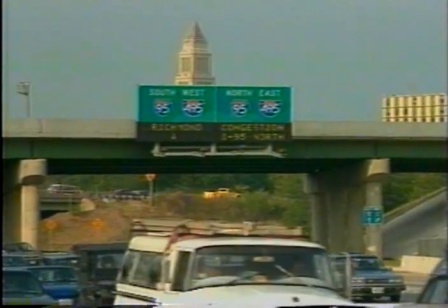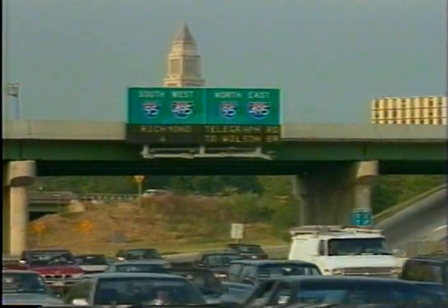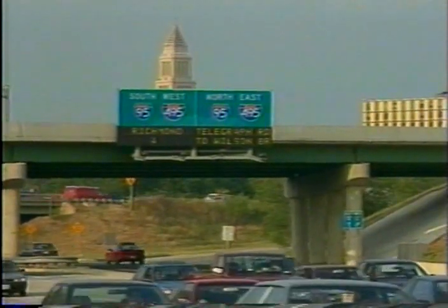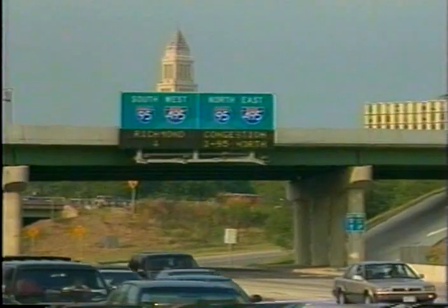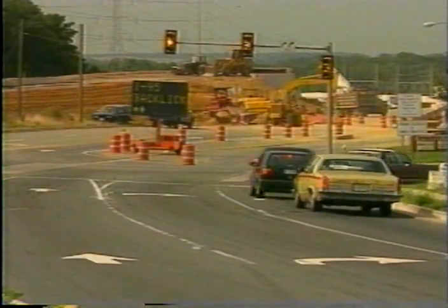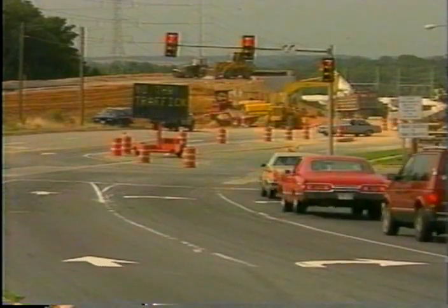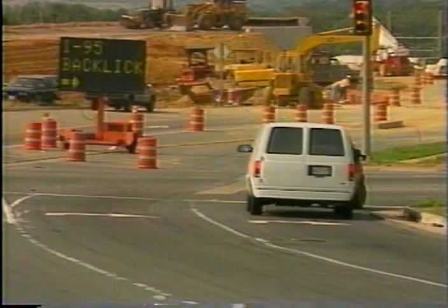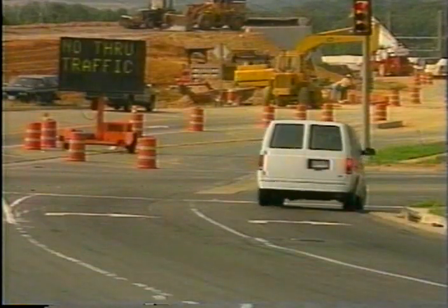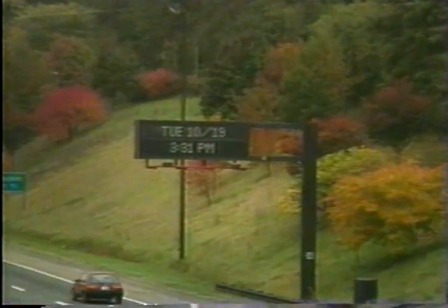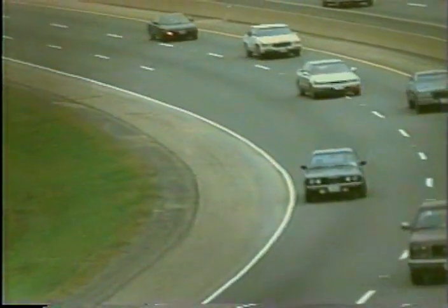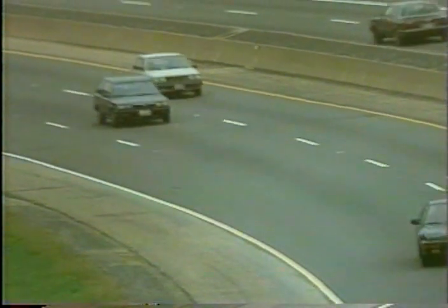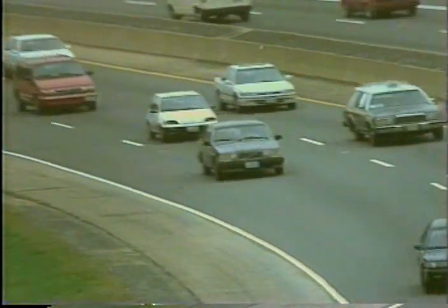Changeable message signs are signs that can have one or more messages displayed or deleted, depending on road and traffic conditions. As the technology improves, these signs are becoming very popular, especially for traffic diversion in congested traffic corridors. The signs can be changed manually, by remote control, or by automatic controls that can sense traffic conditions. Because of technological limitations, these signs cannot conform with traditional signs in size, shape, and color.